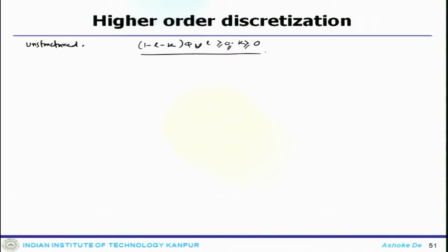So, obviously, if you require less correction, NWF requires less under relaxation, which will lead to faster convergence. So, now we will start from our equation which we are dealing with, this phi f.